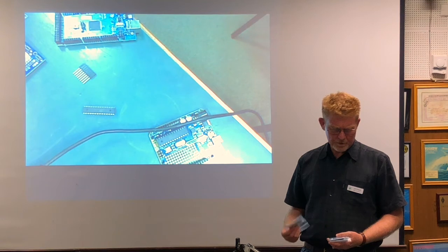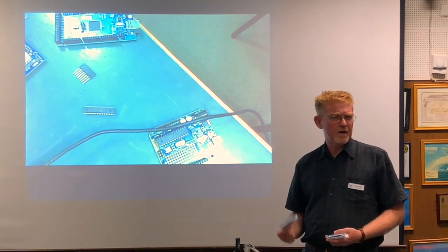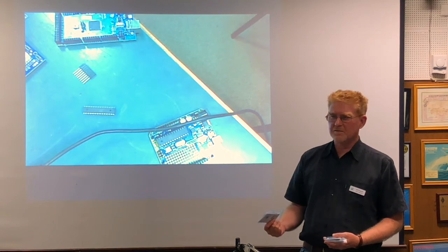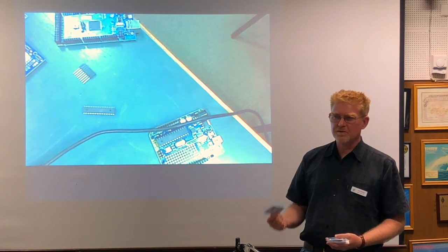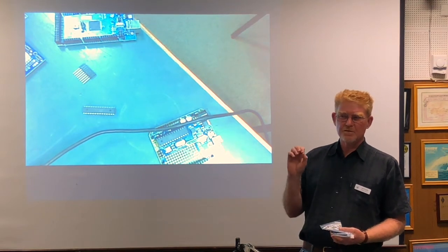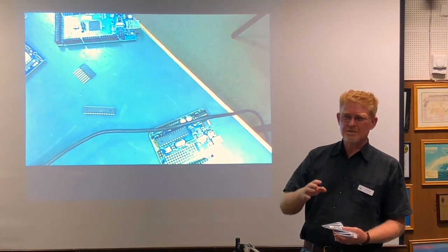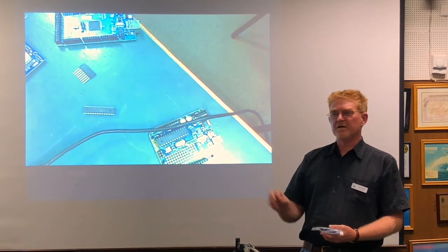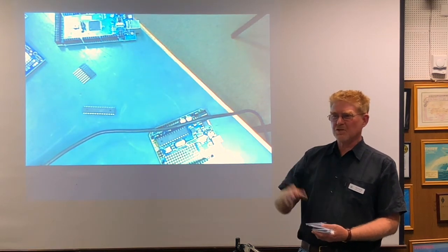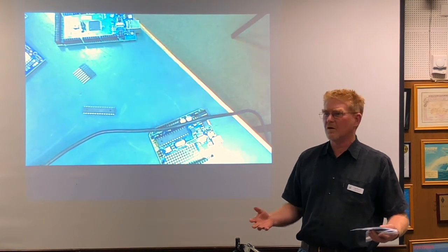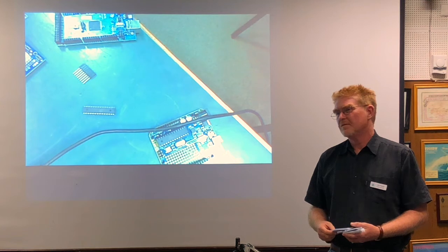There was another company, I think, called Trinamic, who have a Pololu compatible board, which is the coolest thing I've ever seen because it drives stepper motors using analog rather than digital, so it uses a shaped sine wave rather than square wave. The beauty of that is there's no jitter, so for things requiring accuracy, there's basically no flapping around, and they're dead quiet. All the step noise comes from that square wave coming through. These don't use square modes, so you look at it, it just moves. It's like, what's going on? That can't be right.